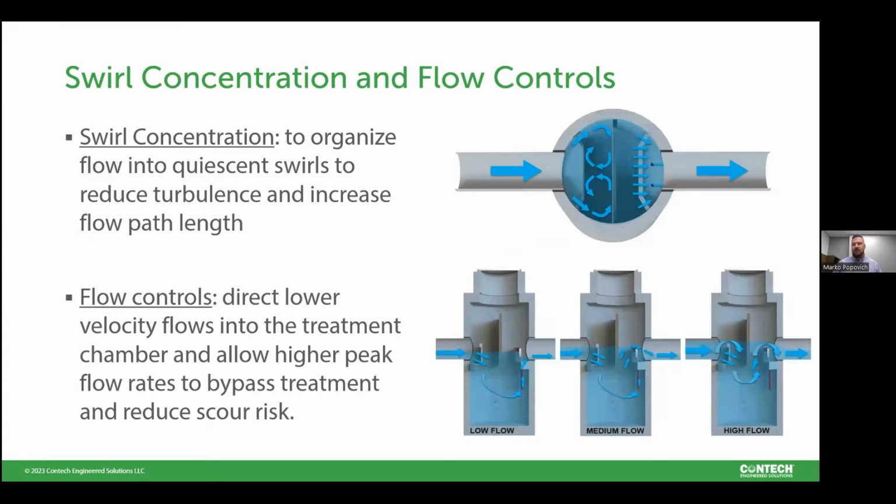This one better illustrates what that actually means. How does it take water and separate the solids that are in that water? On the top right hand side, you can see the swirl path that's created from that inlet splitter, and that ultimately elongates the flow path, which increases settling time for those particles. Therefore, we're able to capture more within a given unit.